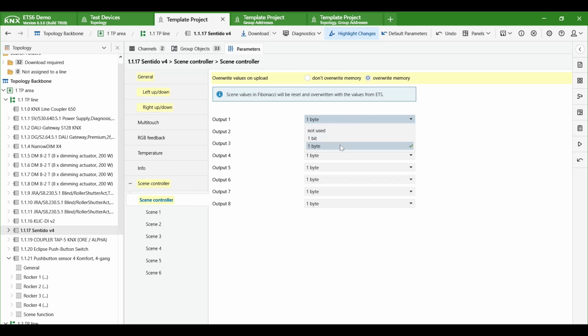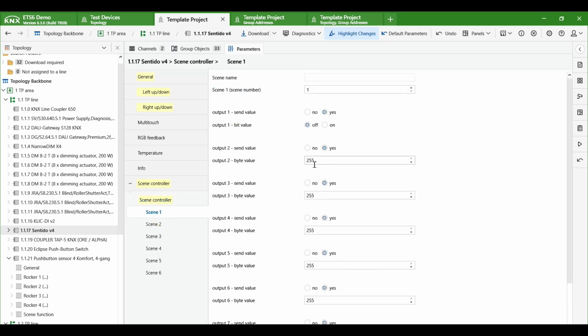Really, it's most of what you need. So 1-bits can turn things on and off, put blinds up and down, do things like that. Where 1-bytes can do modes, fan speeds, blind positions, percentages, all those kind of things. So, you know, it's not quite the same. It's a little bit less effective, and you need to know a little bit more. So, again, instead of putting the blinds up or down, we've got to put them to 50%. We've got to work out that it's 127 on a 1-byte command. So, again, not exclusively used.